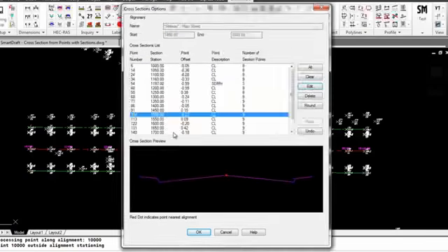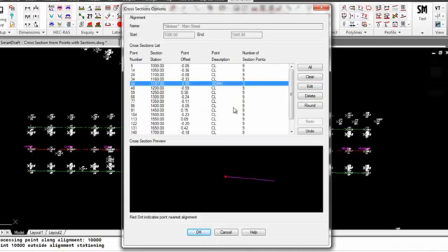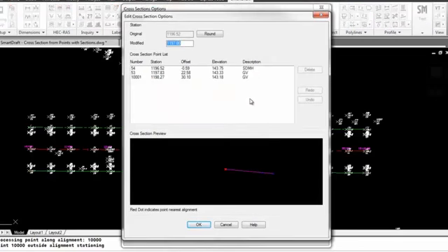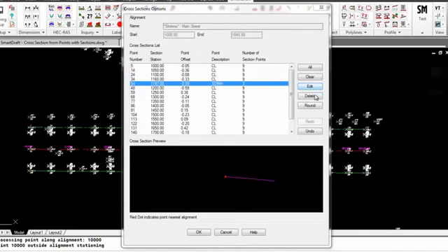Now we have sections that seem to be much nicer, but then we have this interesting section that, if you were to look at the edits, we have the sewer manholes and gas valves. So those points, more than likely, are not considered a real cross-section, so we can delete them. But notice the sections that are near. Here we have 9 points in that section, 9 points in this section.